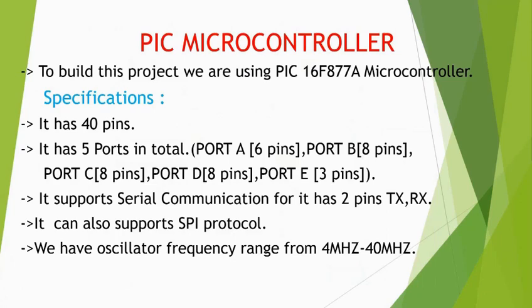This is the next slide of PIC microcontroller. To build this project we are using PIC 16F877 microcontroller. The specification of this PIC microcontroller: it has 40 pins, it has 5 ports in total: port A, port B, port C, port D, and port E. Port A is of 6 pins, port B is of 8 pins, port C is of again 8 pins, port D is of 8 pins, and port E is of 3 pins.